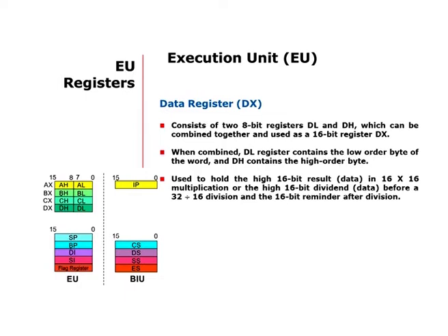This DX is used to hold the high 16-bit result in case of a 16-bit multiplied by a 16-bit, or the high 16-bit dividend data before a 32-bit divided by 16-bit, and the 16-bit remainder after the division. These are the uses of the DX register.